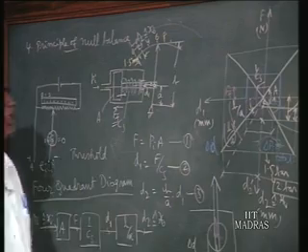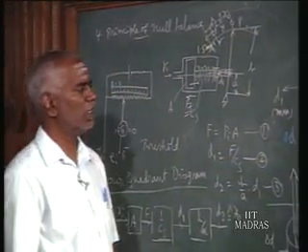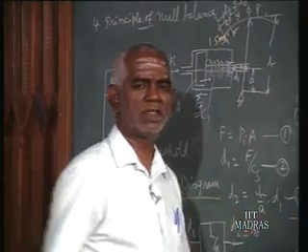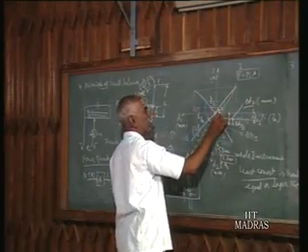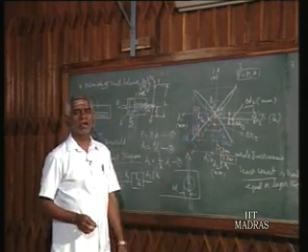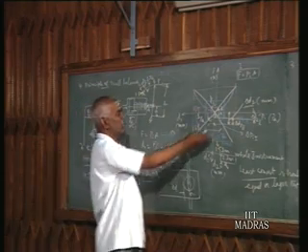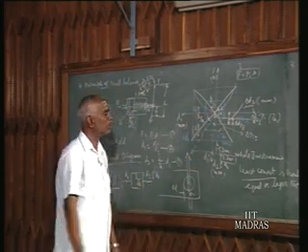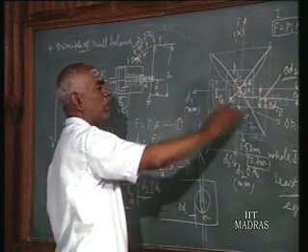But here it is a linear characteristic instrument. In linear characteristic instruments, we need not go for the graphical construction, we can compute also. If it is a non-linear characteristic, computation will be very laborious, and in such instances the 4-quadrant diagram is very handy. We can have the non-linear characteristics, plot again and find out the error.